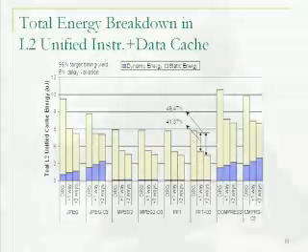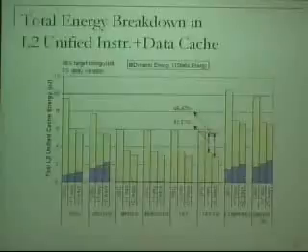For the L2 unified cache, it would serve you even better, because in L2 cache the amount of leakage is higher. The share of leakage to dynamic power is much higher in this case. But in data cache, it does not help you as much as before. The main reason is that in instruction cache, you have the sequentiality point. The basic power consumption mechanism in set associative caches is due to tag comparisons.